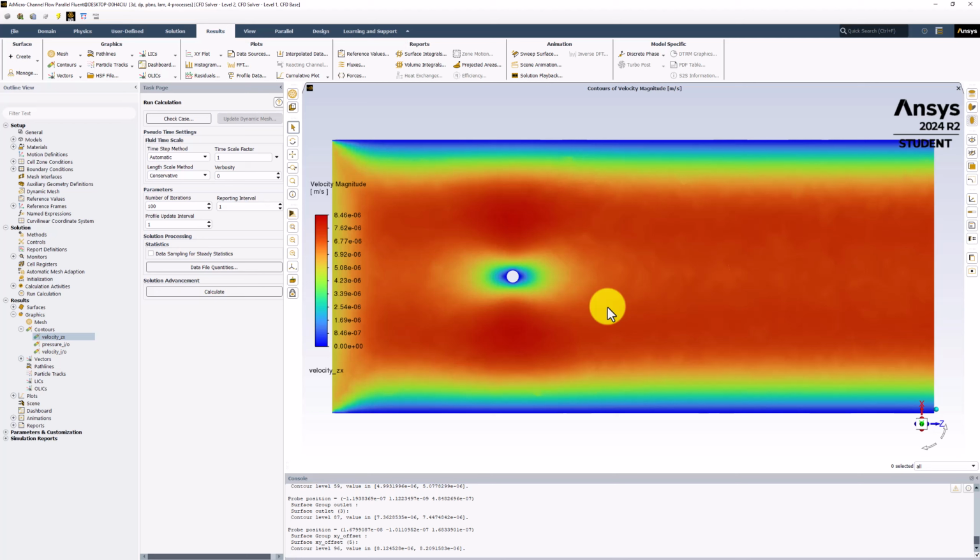Here, we can see the flow as it moves around the obstruction. We can see the flow is slowed as it approaches the cylinder and reaches a stagnation at the frontmost point, as seen in the velocity vectors. Away from the cylinder, we can see that the velocity increases slightly as the flow moves around it. The cylinder effectively reduces the flow area and therefore increases the speed. This occurs symmetrically from top to bottom as expected.